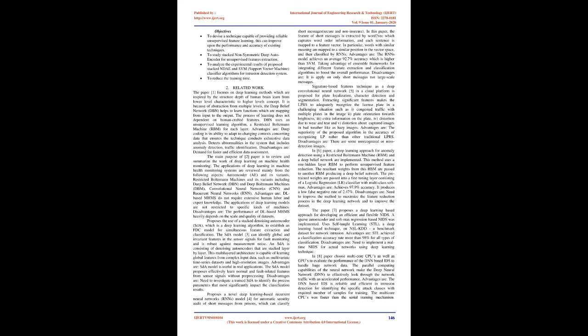Paper 3 proposes the use of a stacked denoising autoencoder, SDA, which is a deep learning algorithm, to establish an FDC model for simultaneous feature extraction and classification. The SDA model can identify global and invariant features in the sensor signals for fault monitoring and is robust against measurement noise. An SDA consists of denoising autoencoders that are stacked layer by layer. This multilayered architecture is capable of learning global features from complex input data, such as multivariate time series datasets and high-resolution images.